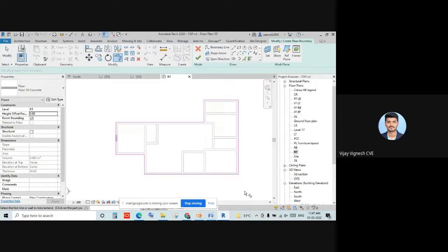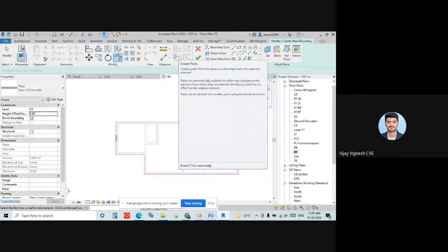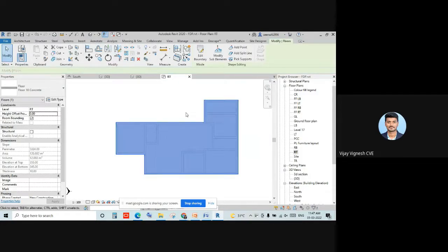Once I have selected everything, like you said, I should click the tick button, right? Yes, right, the Finish tick button. It is saying lines cannot intersect each other. So I have to continue, and then go to trim, right? Yes. The intersected portion you must trim by using the Trim or Extend to Corner. After trimming, just finish once again.